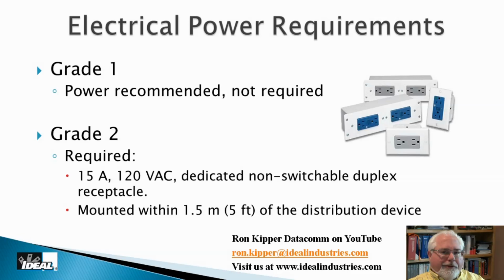And just a little bit on surge protection. I tell contractors that if you're not installing whole house surge units in people's homes, you're missing the boat on an opportunity here. You can run out and buy them for $100, $150, whatever they are. They wire into any 2-pole breaker in an electrical panel. It's pretty simple to install. You can protect your power lines through those. You can run your phone lines through those for protection. They tell you can run your cable TV lines through them, but watch out. You'll find out no cable companies recommend surge protection because at times that device can actually filter channels on them, so that's why they don't like it.